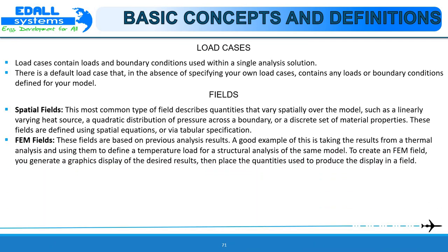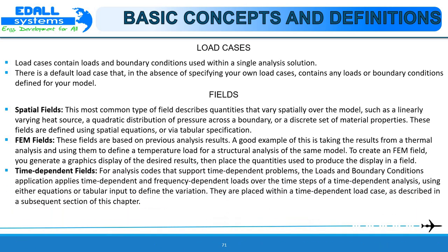The next one is the FEM field. These fields are based on previous analysis results. A good example of this is taking the results from a thermal analysis and using them to define the temperature load for a structural analysis of the same model. To create an FEM field, you generate a graphic display of the desired results and then place the quantities used to display the field.